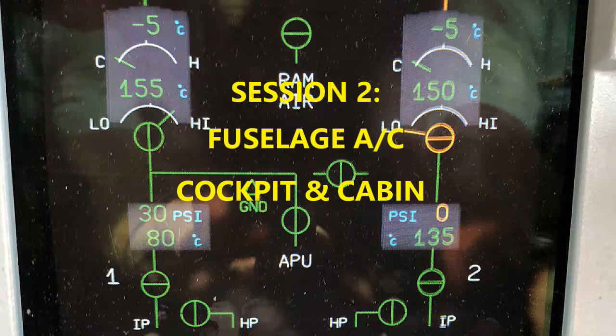You do have a feedback module as well. The feedback module is a rotary variable transformer that's going to send position data to the controllers through the outflow valve electronic boxes. That's what those are there for. Okay, so that information is going to the cabin pressure controllers. You also have the gearbox, and I mentioned that. The gearbox is going to transfer that movement from the activated motor to the outflow valve flap.